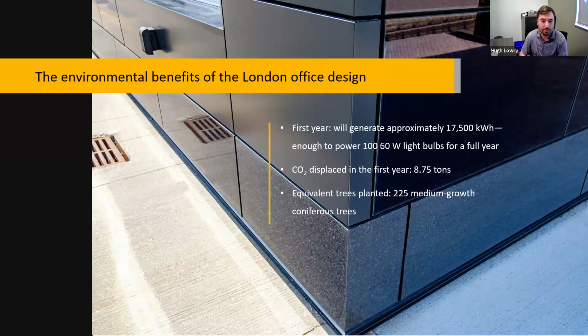I also love this slide because it showcases the importance of having multiple products on the same facade. You can see the solar panel up there to the top right. Key thing to note about solar panels right now is that they're made of tempered glass. You're not able to miter them or return them. So you need to think about a material that's going to surround, accommodate, and complement the solar material itself.